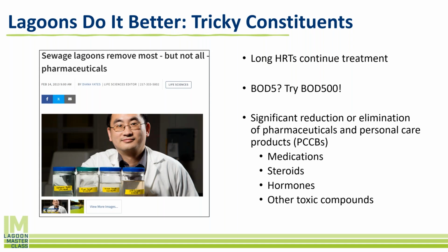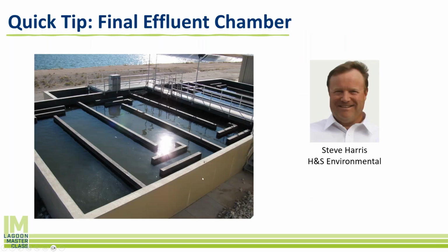But because lagoons hang on to the water so much longer, the different microbes and bacteria have a longer time to break down the proteins and different synthesized chains in those pharmaceuticals to make them inert and make them not a problem for the environment we're discharging them to. So we always like to say that someday we might have replacement of mechanical plants with lagoon systems because of the constituents they treat down to lower levels that are not practical in those mechanical plants.